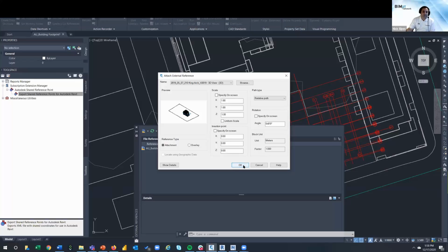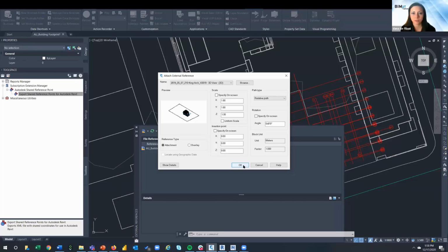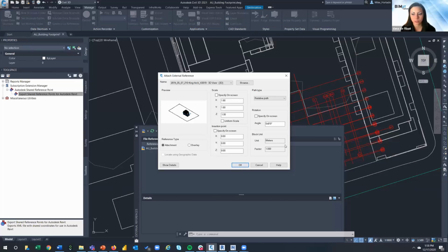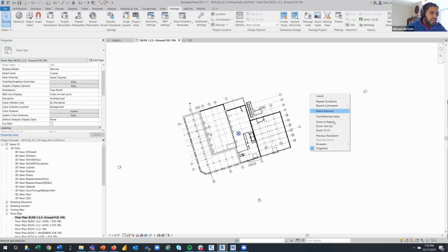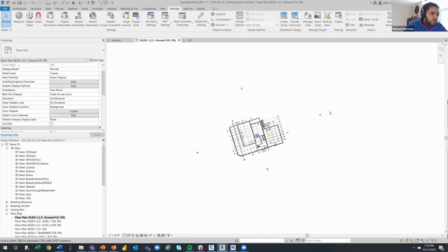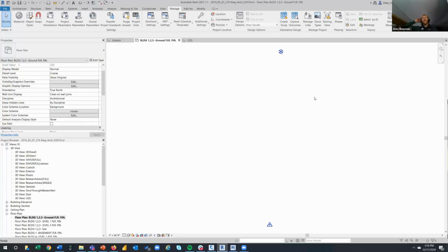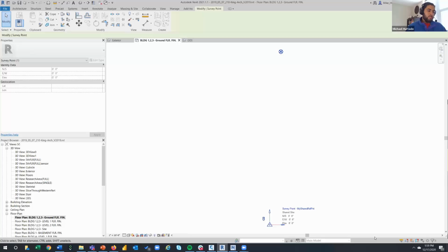Yep. And in Revit, Michael, can you show us where the survey point went to? Maybe the zoom extents. It went really far away. Let's go. Zoom. No, it's not going to be zoom out. Is it? Yes. Again, ZE. So yeah, the survey point is way down here. It's going to remain at 0, 0. So that's why it jumps, because it's actually not a jump. It's everything moves except the survey point out in the space.